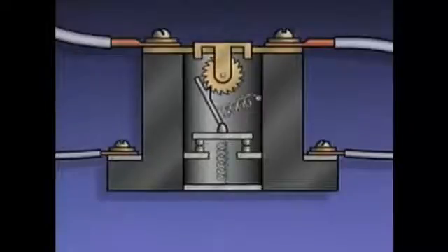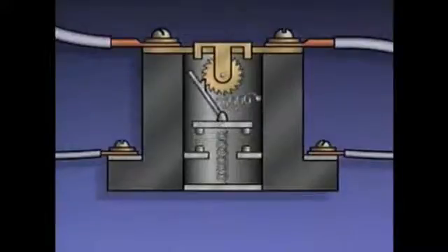As long as the ratchet wheel and the rod do not turn, the contacts remain closed and a complete circuit to the motor controller's main contactor, or M-coil, is maintained. The contact spring is positioned so that its force works on the mechanical linkage to attempt to turn the ratchet wheel. When the current level causes the heater to generate enough heat to melt the solder, the liquid solder cannot hold the rod,